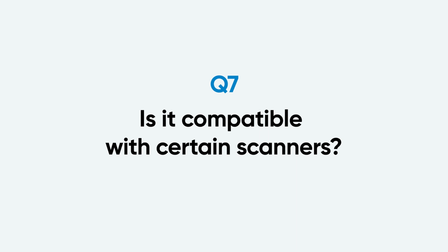Okay, this is the last question for the day. Is it compatible with certain scanners? No, DentBird Crown is an open type CAD, so STL, OBJ, PLY, the scanner model doesn't matter as long as the quality of the scan data is decent. Oh, except for 3Shape, because they use DCM file format, so they must be converted before uploading to DentBird Crown.